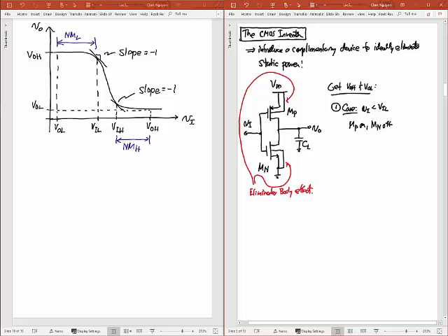And so if we have this situation, then we kind of have this. We have VDD, and if I represent my transistor again by a resistor, I'm going to call this RP on. It's sort of a resistor in series with a switch. So that's RP on there. This is going to be my output here, with a load capacitor. So that's the PMOS transistor above.